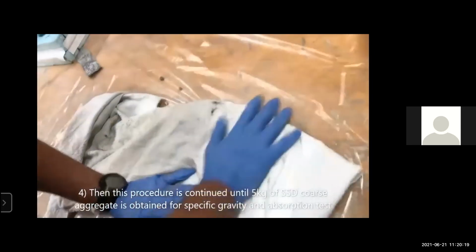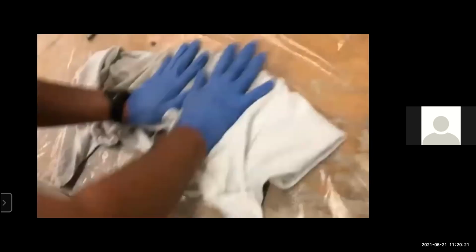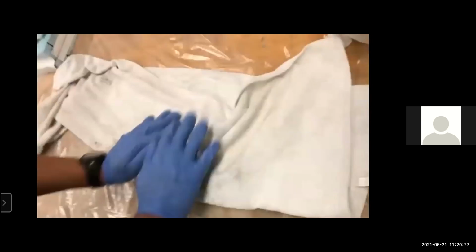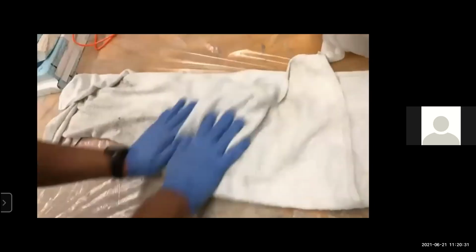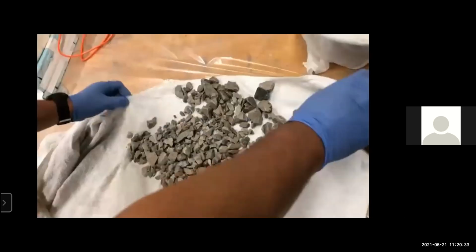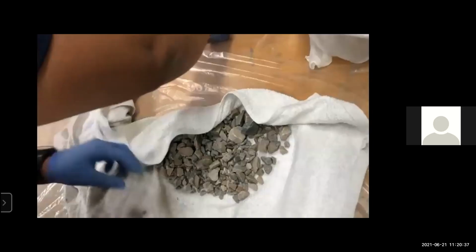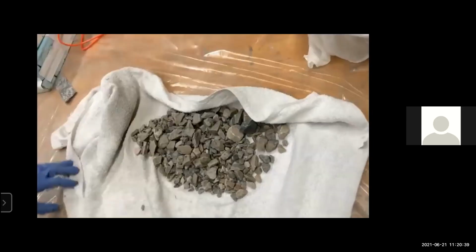Then this procedure is continued until 5 kg of our SSD coarse aggregate is taken for our specific gravity and water absorption test. So keep in mind that for our specific gravity test and water absorption test, we generally take 5 kg of sample.